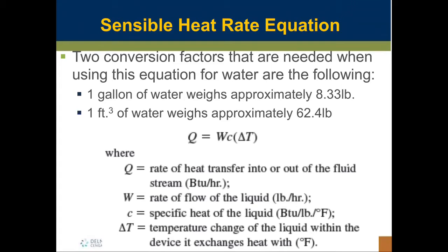All right, moving on to this next one. Let's try to plug some numbers in so we understand this equation and what we're doing with it. The BTUs per hour is identified as Q, which equals the rate of flow times specific heat times the delta T. We have a couple of factors that I want to identify as characteristics of fluid.